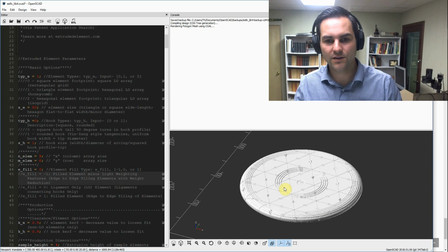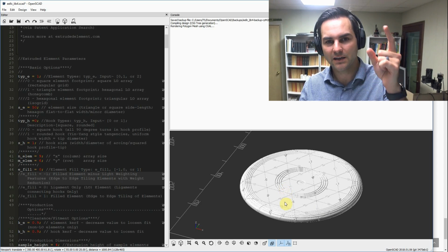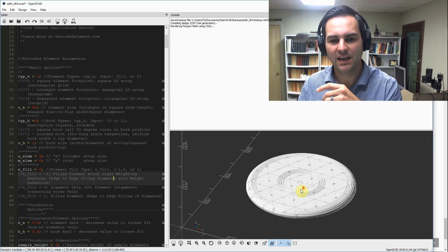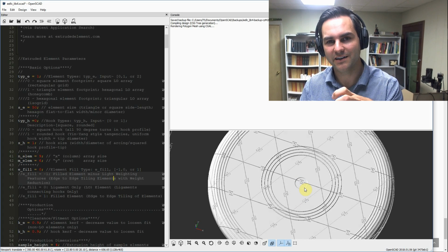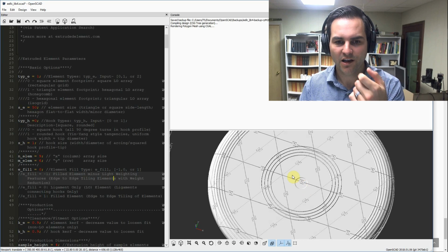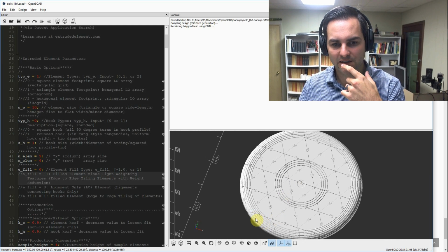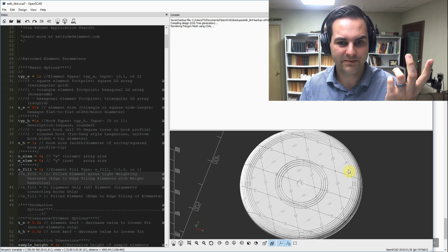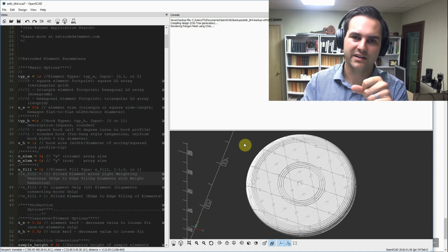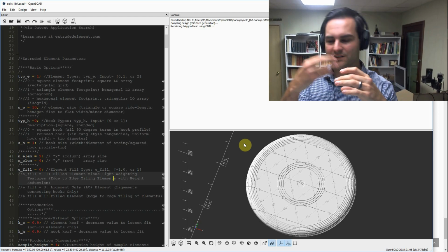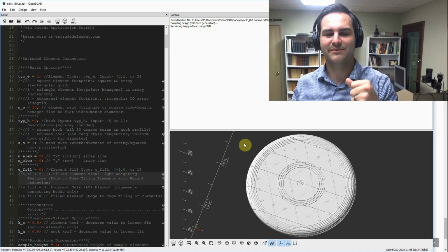And even though there are 54 elements, the STL files that you'll find in that directory after running the batch file will only be this many. So maybe 25 elements, 30 elements will actually exist because the rest had no renderable geometry with that intersection command of intersect imported object with extruded elements.